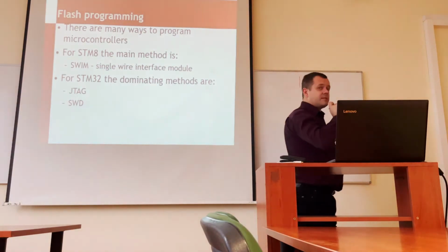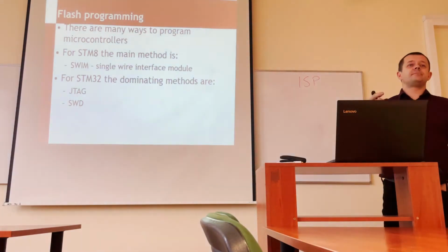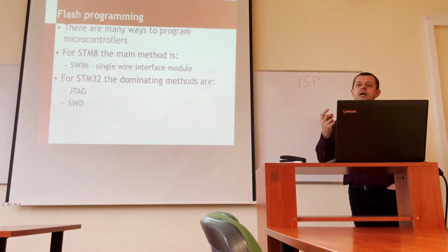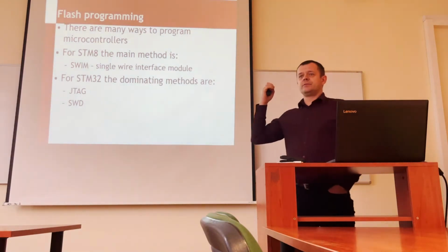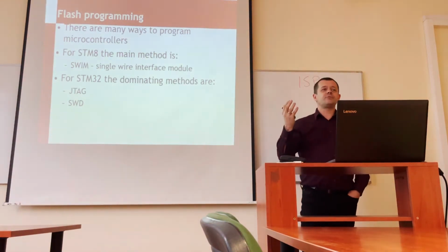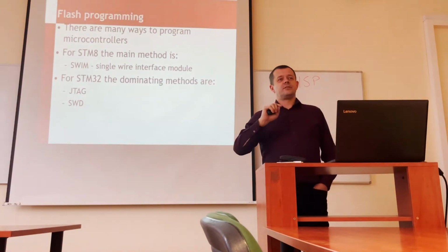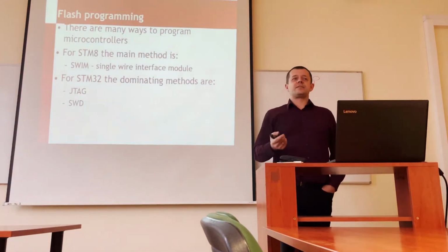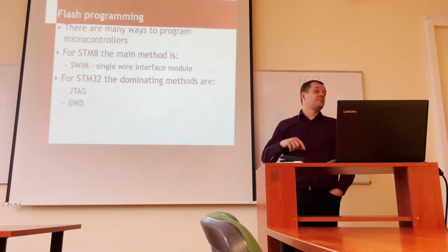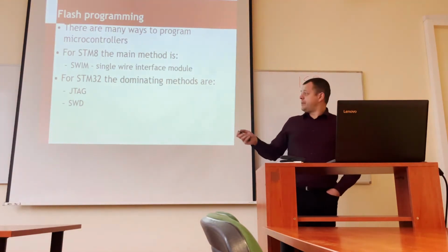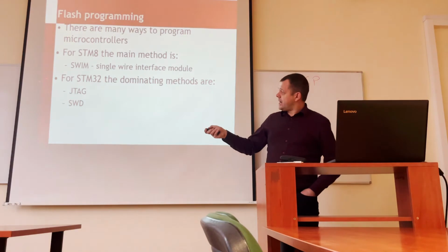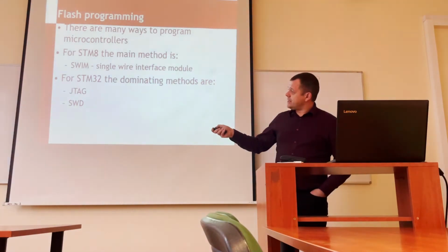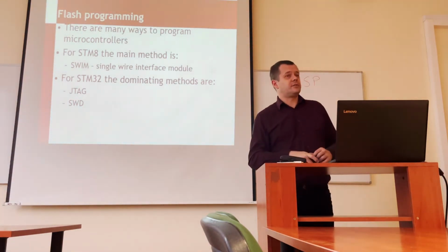Today, programming is not enough. The second problem when you want to work with microcontrollers is to have access to the registers, to go a step further beyond programming, to access the registers and to do debugging. For debugging, the standard interface in the industry is the so-called JTAG interface.